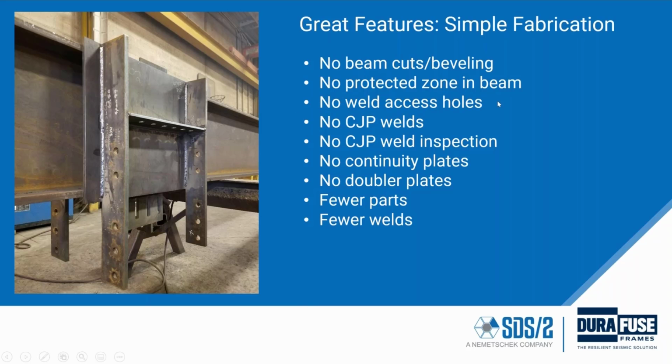There's no protected zone in the beam. There's no weld access holes, no CJP welds or weld inspection. There's no continuity plates. Those are very expensive with CJP welds on them. There's no doubler plates. Overall, there's fewer parts and fewer welds than other moment frame connections. So great features for the shop and for the fabricator.